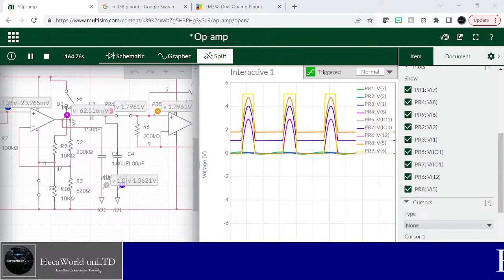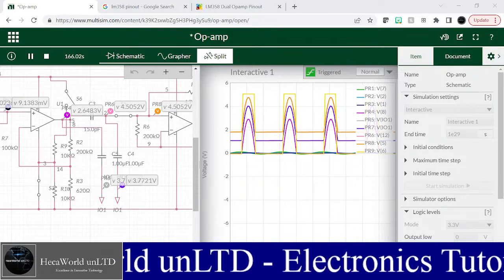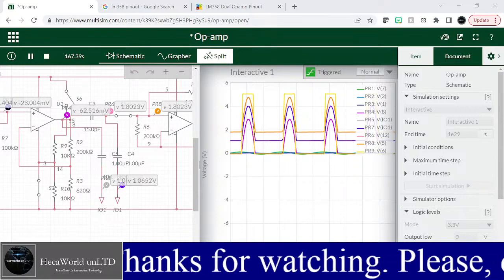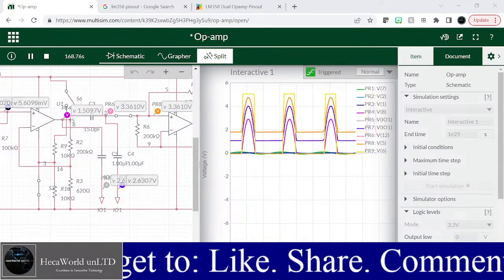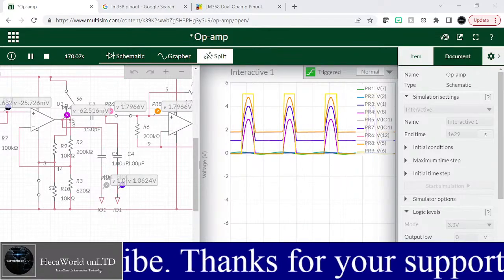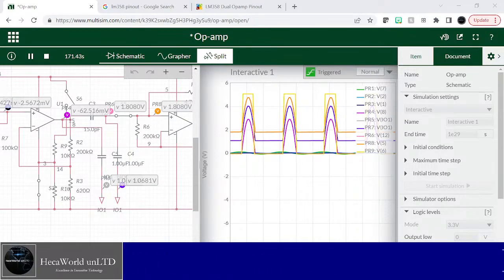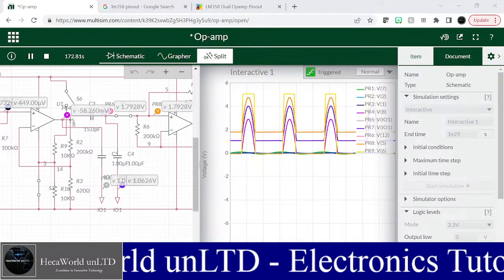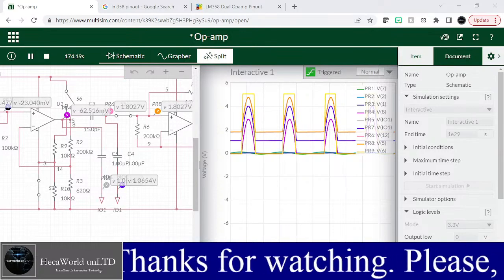All right, so the modification we did was, first of all, we don't want to build a Schmitt trigger system because we want to convert the system to an audio amplifier. And as you can see, even without my explanation, you're getting only half of the signal. Every sinusoidal signal should have the positive side and the negative side, but all we have here is the positive side. The negative sides are truncated because this was not taken into consideration during the design.